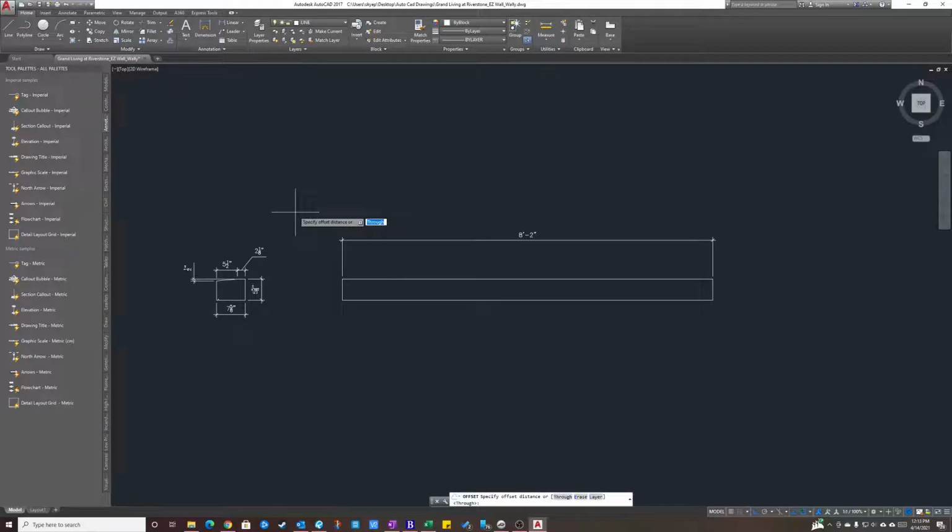Let's say we're going to offset it by 1/2 inch. So you click offset. It's asking for a through dimension, which is 1/2 inch. So 0.5. We're going to click on this top and we're going to drag it down. But you see how it just made another line all the way around? Well, that's because it's one solid piece. So what we have to do is explode this first, make it into individual lines. So we use our explode tool, click on it, right click to activate. Now these are individual lines.